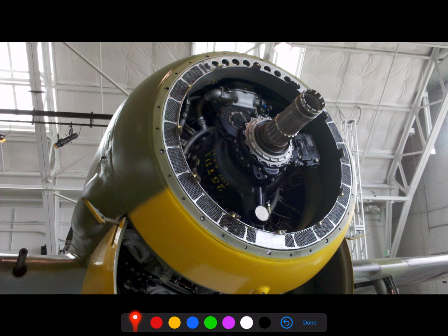What you'll notice is that this entire cowling section here is very, very tight fitting and relatively small compared to a lot of different radial engines and the nacelle setup that they use. One of the reasons this was done was to provide better visibility for the pilot over the front of the aircraft and to reduce the overall size. I'll draw a picture for you that shows how this comes together, but it's very interesting the way this functions. What you will see around this perimeter are attach points for an armor plate which sits right in front of that oil cooler.